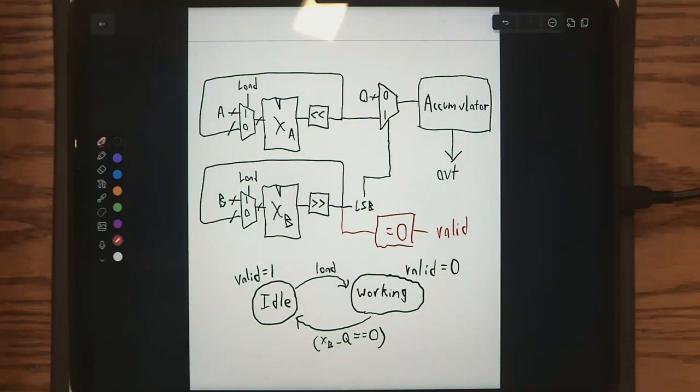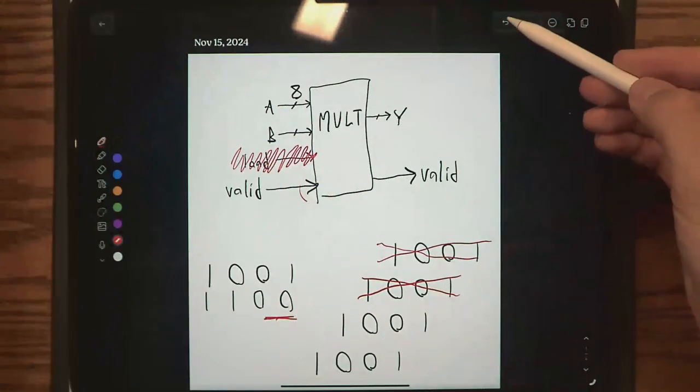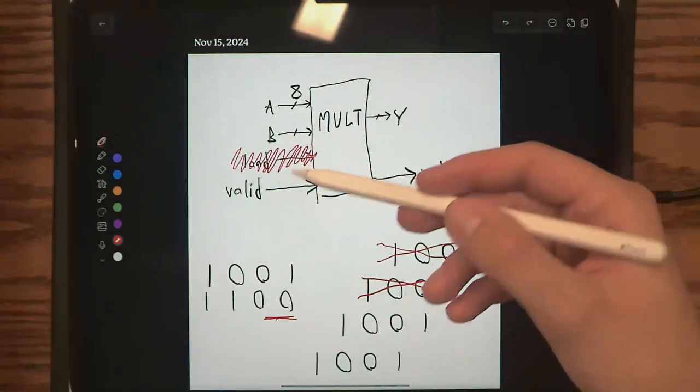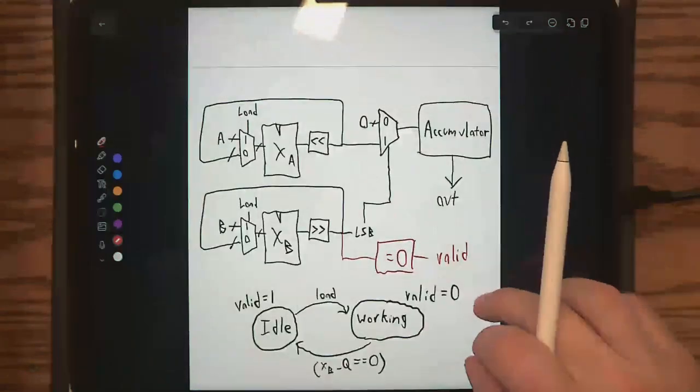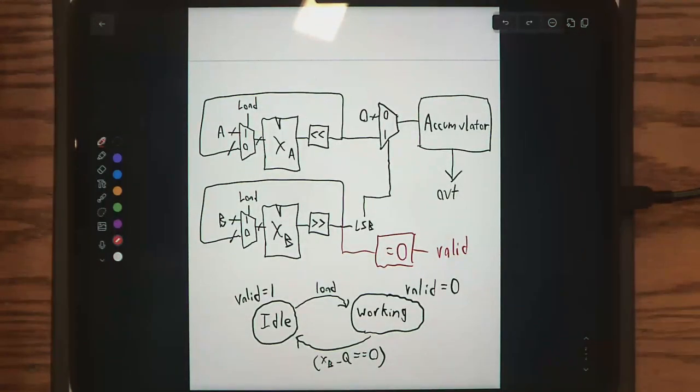Yeah. Should we add another mux and have one of the inputs be load and one of the inputs be 0, and then the select is valid? Ooh, I think that would not actually do anything, because that would basically be the exact same thing as just plugging in valid as load. I guess what I'm thinking is we actually just get rid of load altogether, so we're basically replacing load with valid. But yes, I do agree. We should probably have some sort of extra logic, maybe a mux, maybe a gate or something. Yeah, any other ideas?